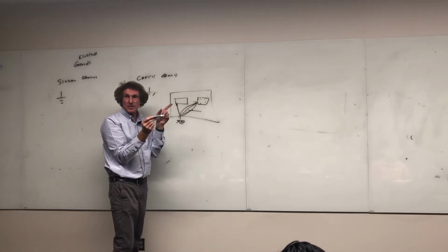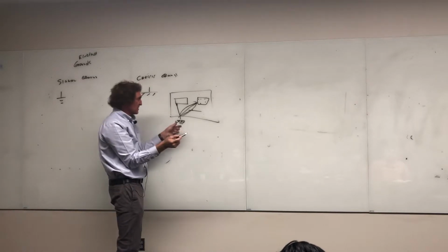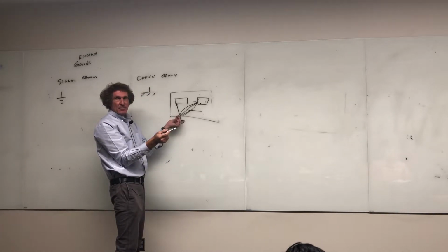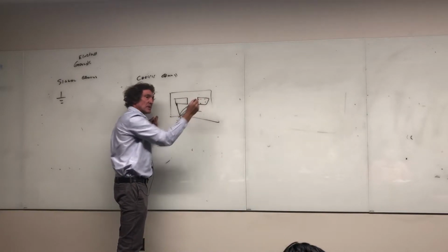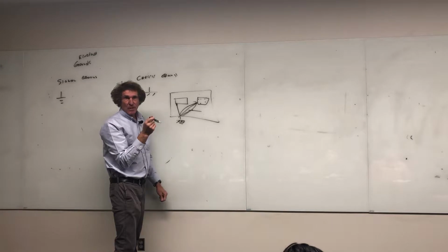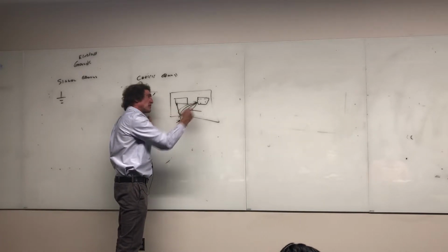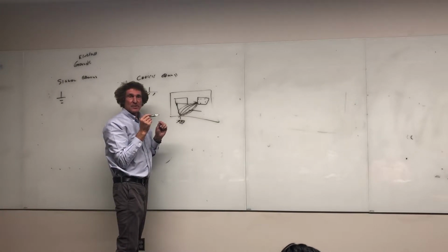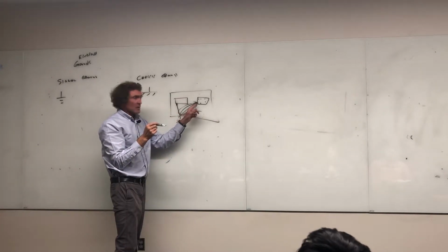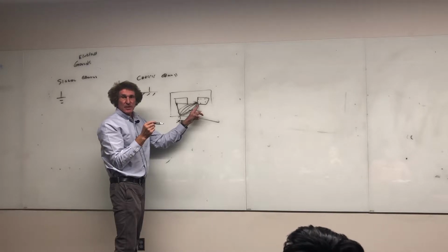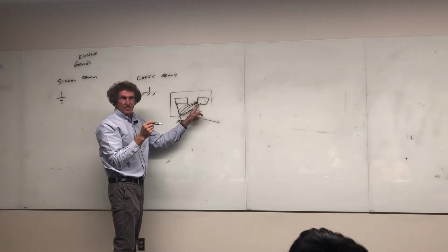All right, do you hear me on this one? Because it's very convenient to tap this thing with an alligator clip, and then take your probe and start measuring voltages there. But the problem is this: if it has a long lead, this will develop a voltage that will cause your readings to be off by that voltage. So you always want to get your ground as close as possible to the board you're measuring. That's the first thing.